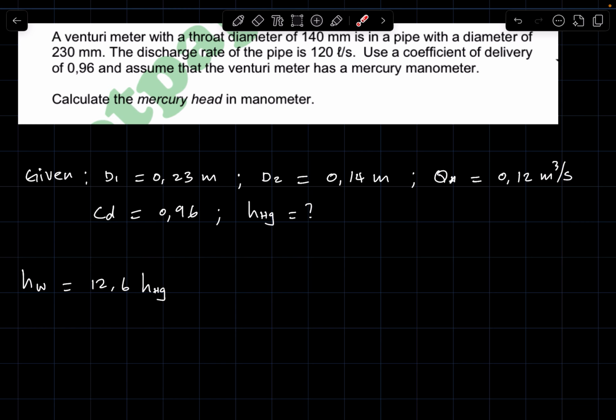So it eliminates one of the velocities between V1 and V2, but there's still the HW, which will be the pressure head difference between 0.1 and 0.2. So essentially, you will have this as an unknown, and also V2 will be an unknown. So which means you cannot take the approach of the application of Bernoulli's.